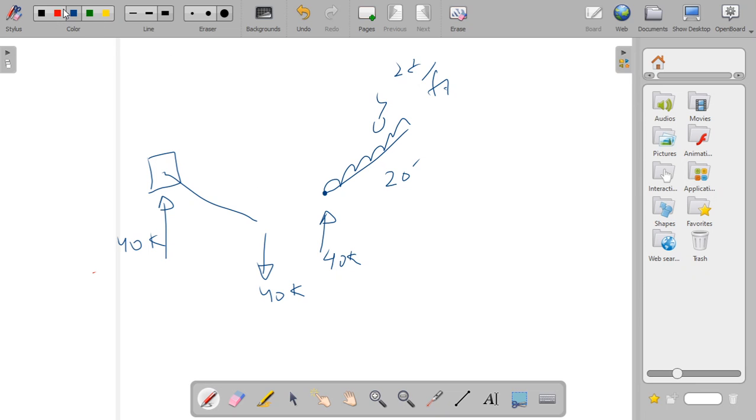Okay, one more thing. This 2 kip per foot is in the y-axis. This member is in the z-axis. So the y-z combination gives us x. A moment shall form in the x-axis. So if you rotate this load towards this joint, which is B, it forms a clockwise moment. So I have to apply a resistive anti-clockwise moment in x. This is Mx, and its magnitude should be equal to 2 into 20 into 10. It comes out to be 400 kip foot.